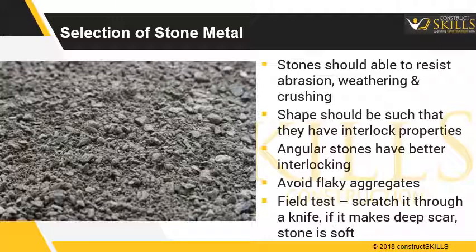Brittleness: use a 250-gram hammer. If the stone breaks easily, it is too brittle. Appearance: the stone should be uniform in color, and should not have any green, reddish, or yellowish tinge.